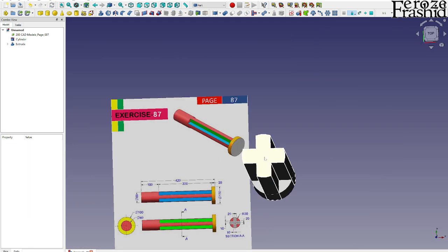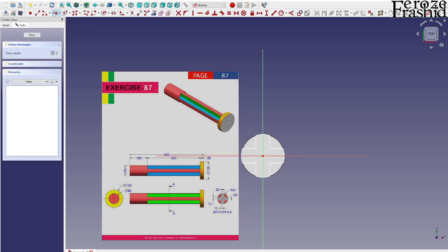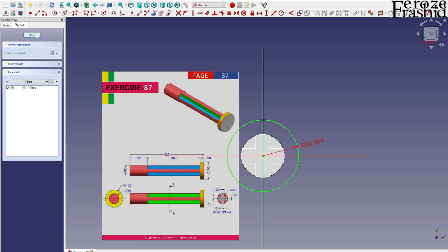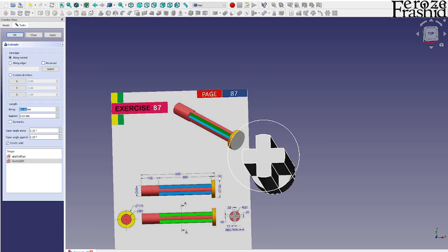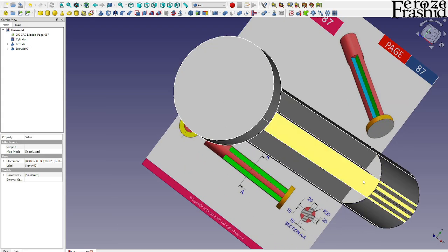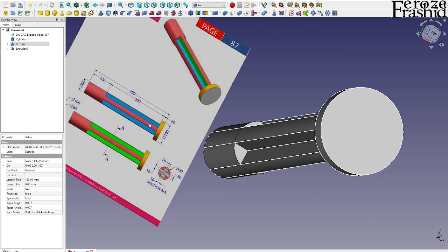All right, and then finally there is a pad, 100 millimeter diameter on top. So let's go ahead and draw another sketch on the XY plane, and it would be on a 420 offset. There I can draw a center circle with radius 50, and then I will make a pad out of it for 20. So notice that this object begins from the bottom. We could have done that from this surface as well, but we will be combining them all together.